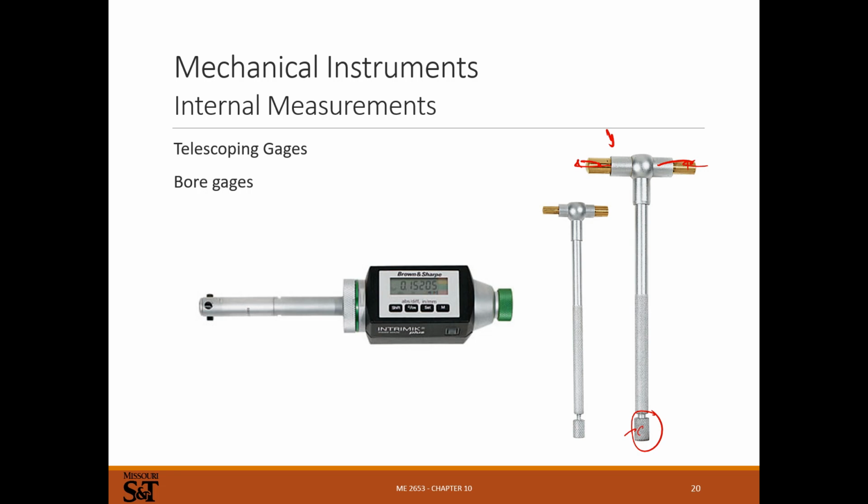And you can see there's lots of places for this to go wrong. So it takes a lot of practice and a very good set of these to be able to get good dimensions using telescoping gauges. I have screwed up a lot of parts with telescoping gauges before. So just like everything else, I know these are a stupid, simple mechanical thing, but buy good telescoping gauges.